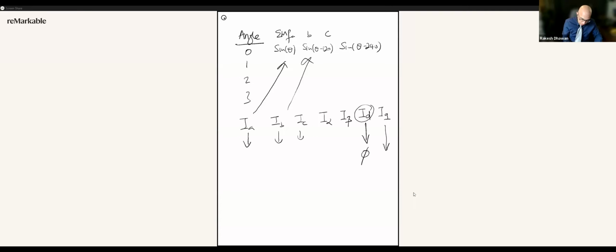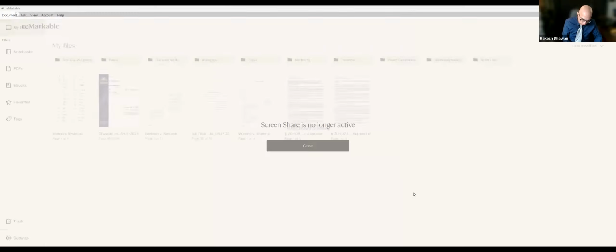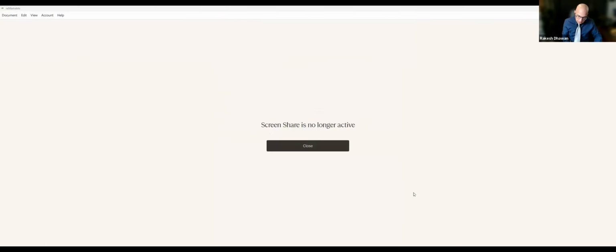And when you do a phase advance, where you put a different theta here, then you will see that ID begins to emerge. These should be DC values, and I alpha obviously should be equal to IA, right? So this would be a good exercise to do.